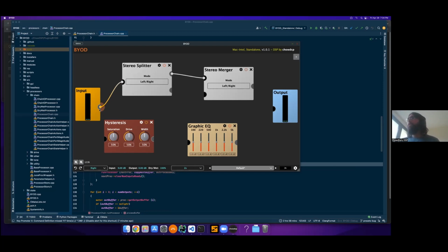Basically the way it works is you have one spline point, which is the center of the dot there. And then you have another spline point that's a few pixels out. It's hard to describe, but without those points, it doesn't feel quite like a real cable because the line goes off in that direction too quickly. So I had to add a control point a few pixels out from each port, and that made it smooth pretty nicely.